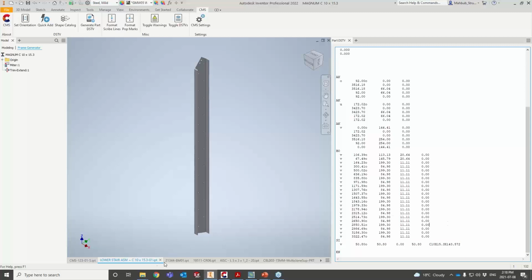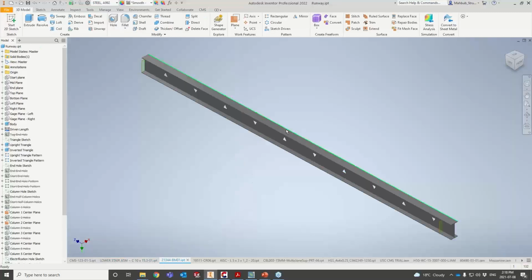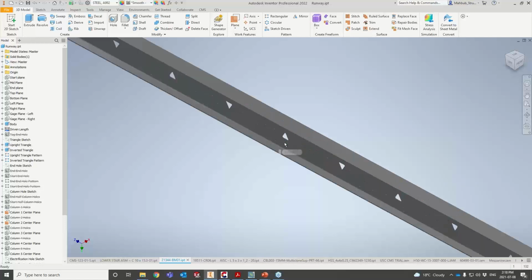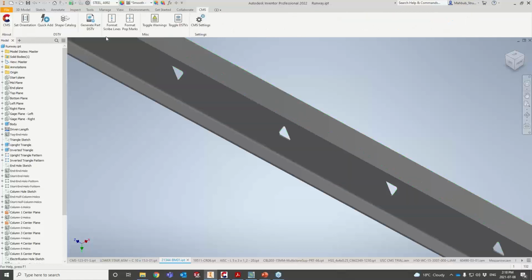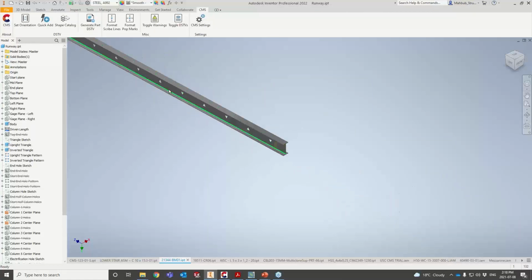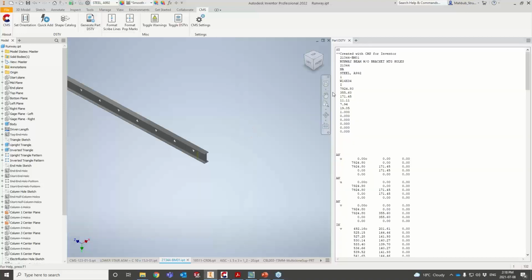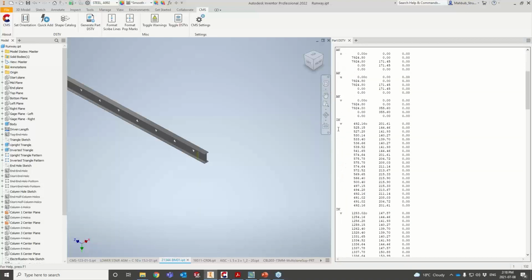It's the same drill. I have shown you all the examples with external cuts and boundaries, but if you have any internal opening, that's not a problem either. It's the same drill: for as many openings, it will just create those IK blocks. IK stands for internal cuts. If you scroll down, as you see, your IK blocks are being created, which is for the opening.